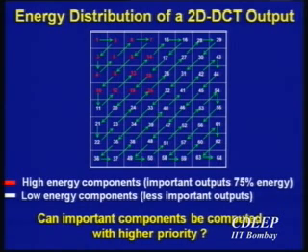And what are these matrices? These are actually a bunch of those cosine computations. And it turns out that if you look at the left corner, that is a very, very important term. Okay, and people do a zigzag through these matrices to determine what is more important. So 1 is very important, followed by 2, 3, 4, 5, 6, and so on. That's the way it's shown. When it comes to images, the corresponding thing one can think about is that 1 is basically a high energy component, and the other ones which go down to 64 here are the low energy components, meaning thereby that if I have some failures in 64, 63 and those bits, then I can tolerate it.